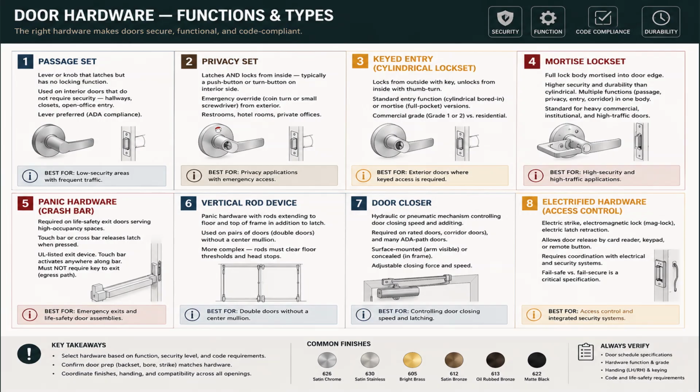to the latch. Used on pairs of doors, double doors, without a center mullion. It's more complex, and the rods must clear floor thresholds and head stops. Best for double doors without a center mullion.